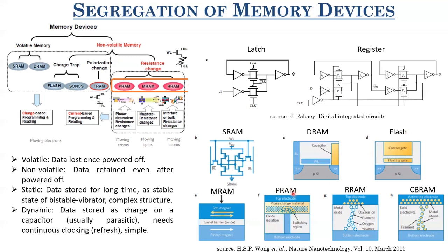In phase change memory, cell currents are very large because you have to melt this phase change material and then allow it to cool. Next is magnetic RAM, or MRAM. MRAM basically builds upon the spin properties of ferromagnetic materials. When we talk about FRAM, we are talking about ferroelectric materials, which show polarization change. Here in MRAMs, they exploit ferromagnetic materials, which show a change in the magnetization.